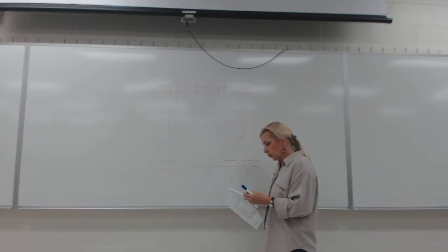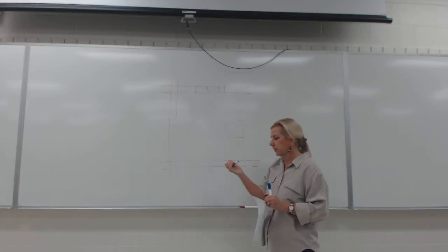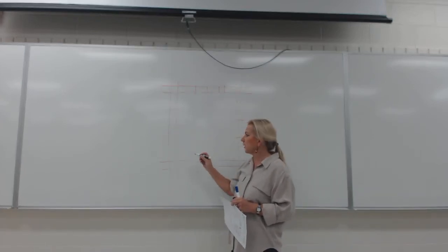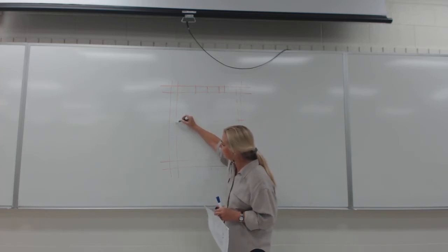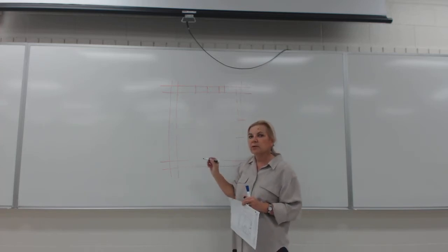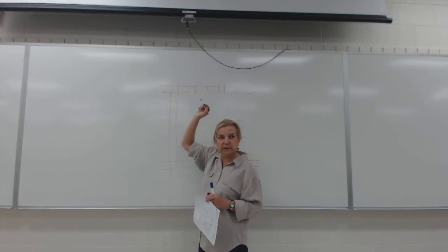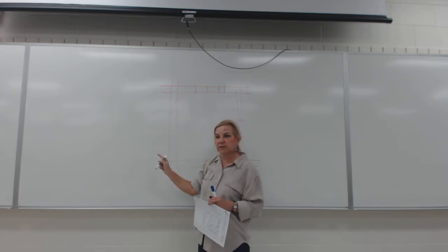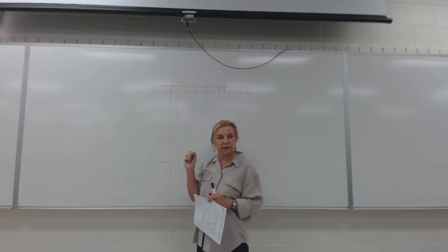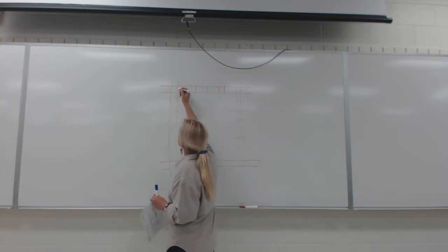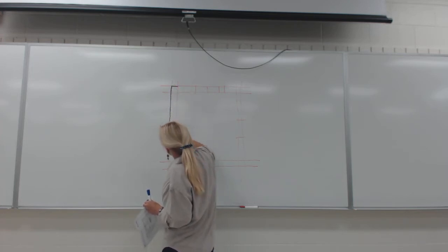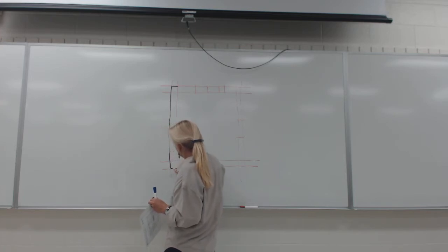So again, summarizing where we should be today with the black marker: we went ahead last week over these construction lines. We've measured them, and we were measuring tiny little points, and we went along them to cover them up. So if you're still measuring corners, remember that that's wrong. If you have light construction lines that have perfect corners, you're no longer guessing, you have the start and end of your dark lines. So you would take a pen and press really hard with your H-lead, and you would finish from start to the end of all of the construction lines, and you would get your final wall.